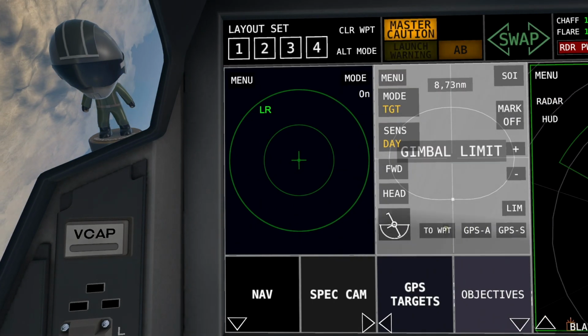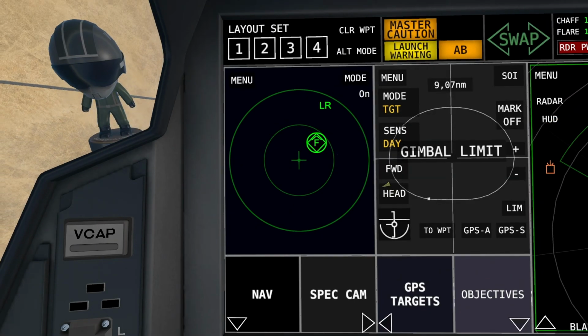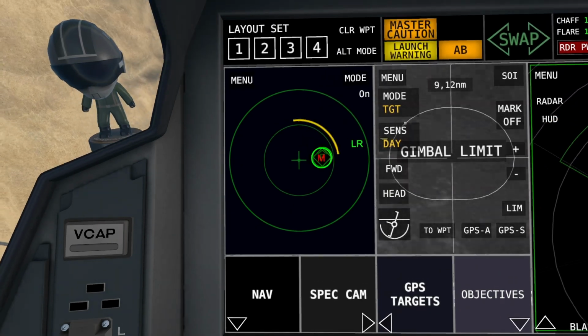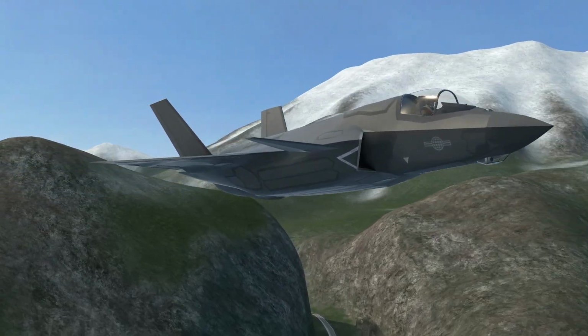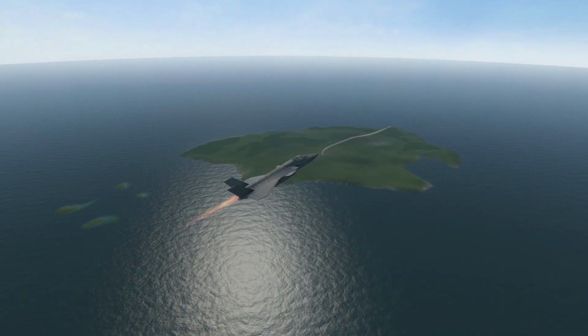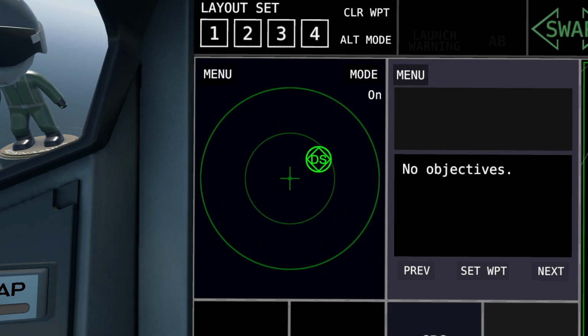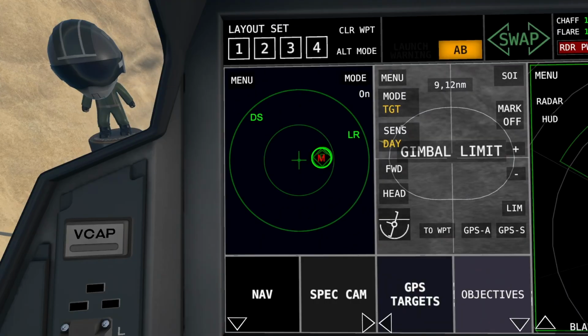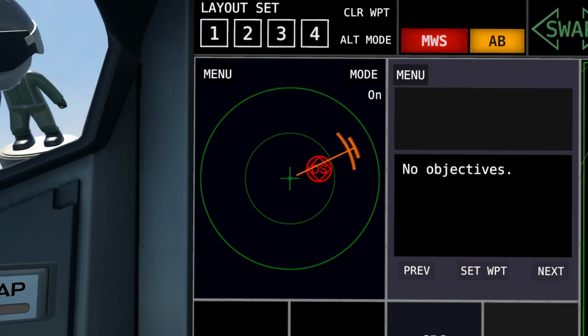The RWR detects a radar signal's direction and also if the radar has a lock onto the aircraft. It's also able to discern between missile radars and ground radars. The MWS uses cameras along the aircraft to detect smoke trails and notifies the pilot if a missile has been launched. Together, these two systems can inform you about radar, radar direction, radar lock, missile launch, missile radar lock, aka pitbull, and missile distance and direction.